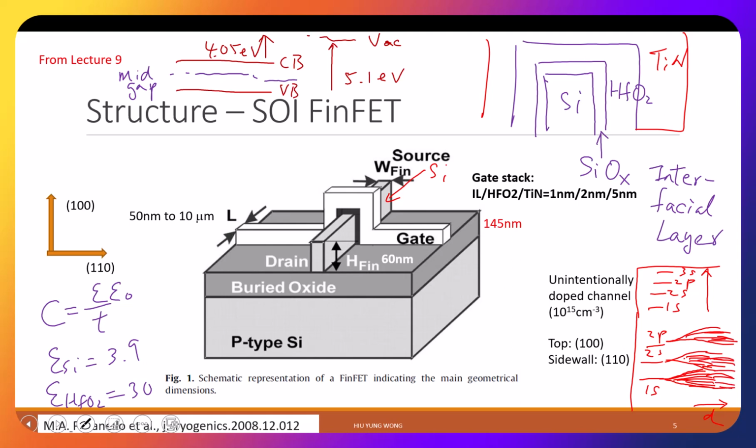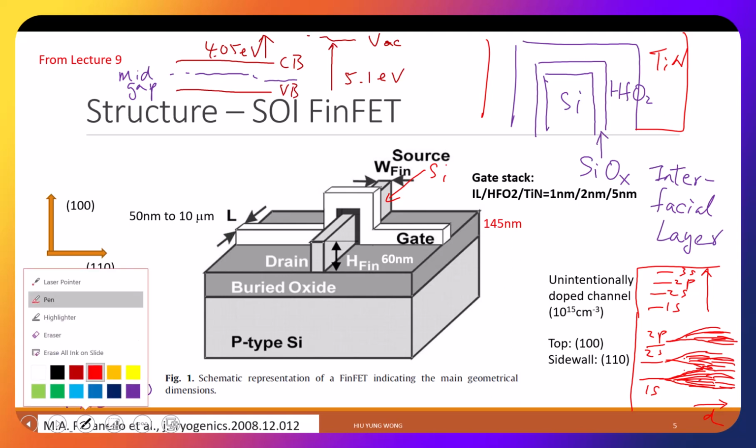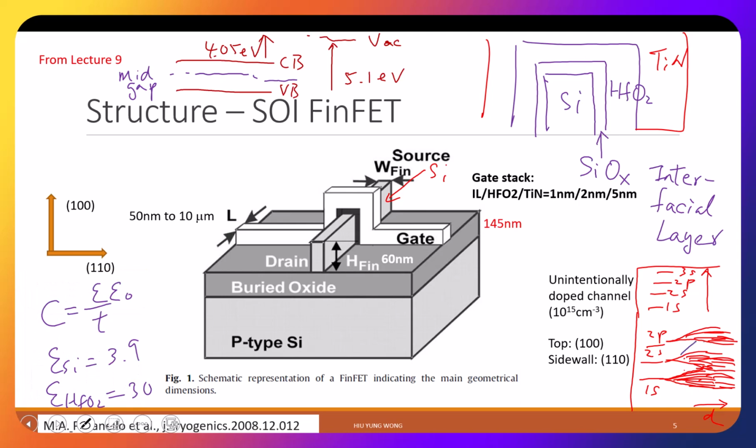And then, of course, you have those so-called anti-bonding also, right? They won't fill up all the way to the top because now you merge them. And the so-called conduction band and valence band is just that there's a band gap in between, right? And for silicon, it turned out that they all fill up those right below the band gap. And then the conduction band is completely empty.